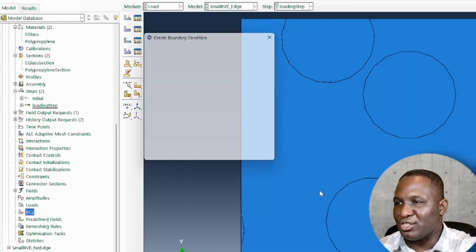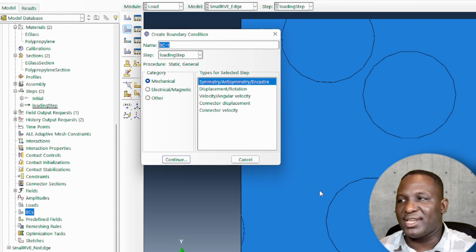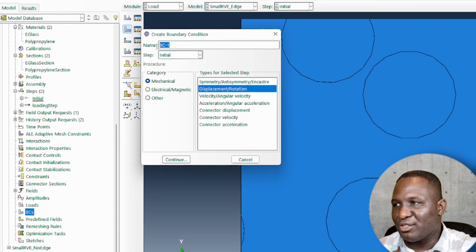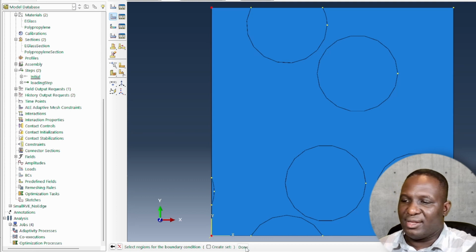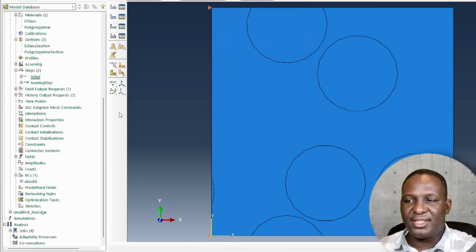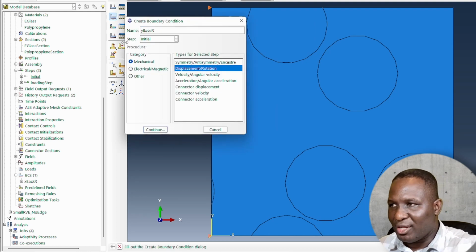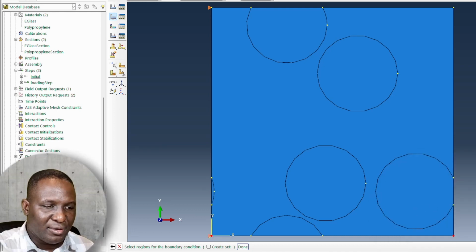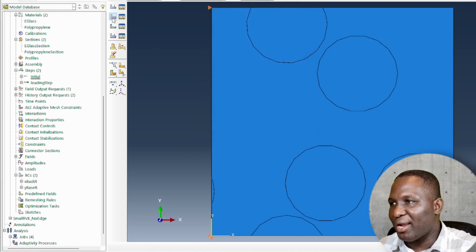Then what about the boundary condition? Because he's going to use periodic boundary condition for doing this, you only have those 4 corner nodes as anchor points that you can use for setting this up. So the initial boundary condition will be X back at the roller. You will only need to use that point and this point as the anchor point, and it's holding it in the one direction. So we'll do the same for the Y base roller. So this point will be held as well in the Y direction.